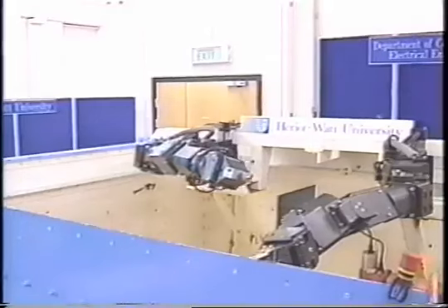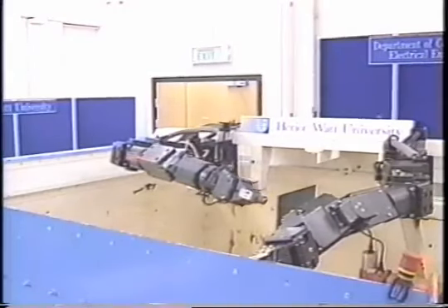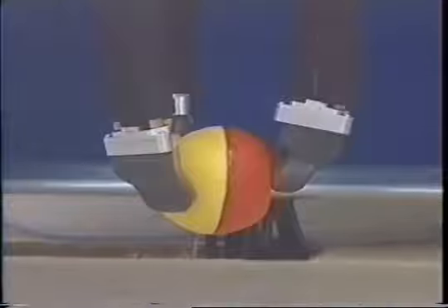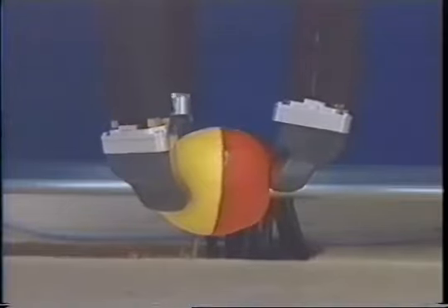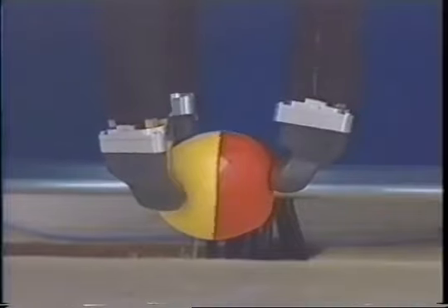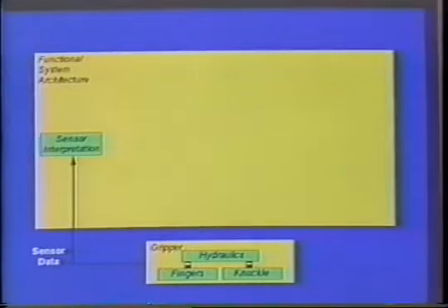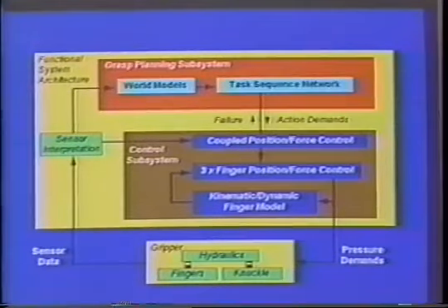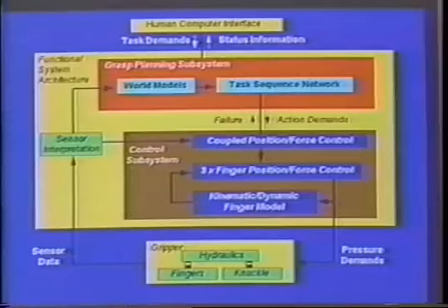The current generation of robots used for remote operations in the ocean have crude grippers with no contact sensing. Amadeus is a collaborative European project developing a dexterous underwater grasping system using elephant's trunk flexible actuators for fingers. The development comprises the gripper mechanism, force and slip contact sensing, coordinated finger force and position control, supervisory grasp planning, and a graphical user interface.